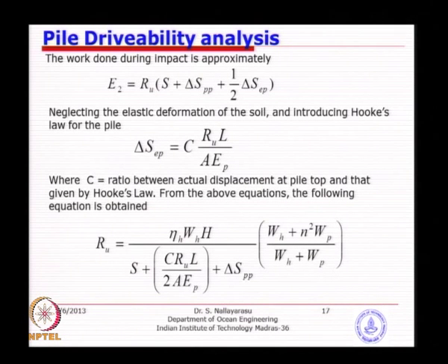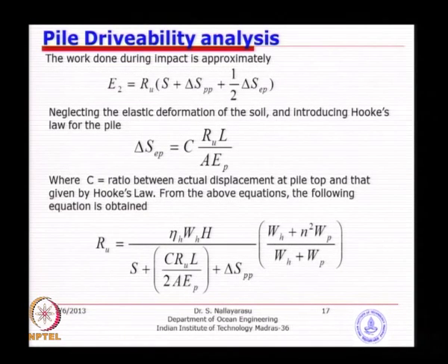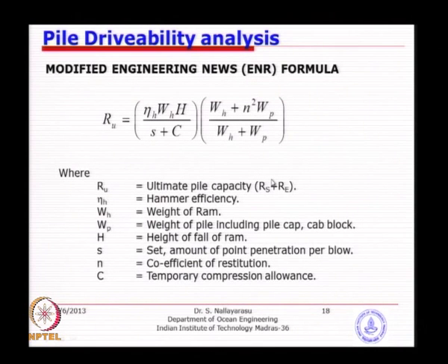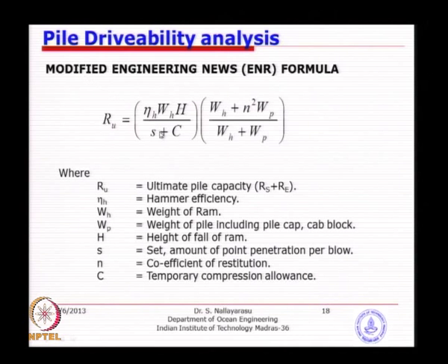We go into slightly more detail. That is the final formula, just rearranging this S, and delta SP has been removed because the plastic deformation is not considered, and rearranging this you will get this kind of formula. This formula has been used for quite some time, even now onshore pile driving people are using it, because it is quite easy. You do not need to understand much. What you need is a hammer weight and the set value that you want to determine as a final penetration, and then resistance against driving or ultimate capacity.